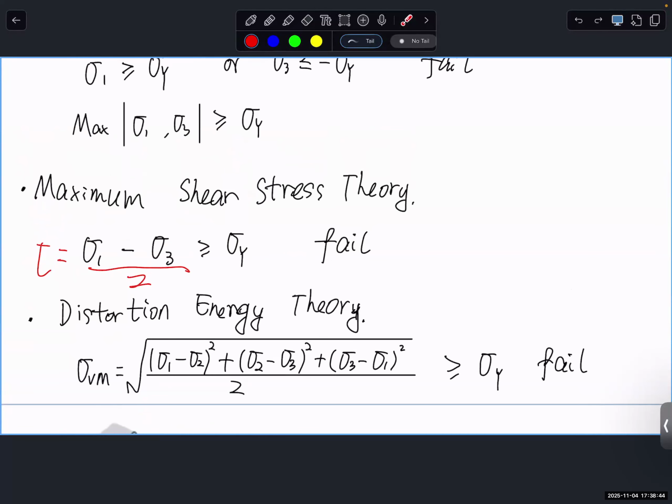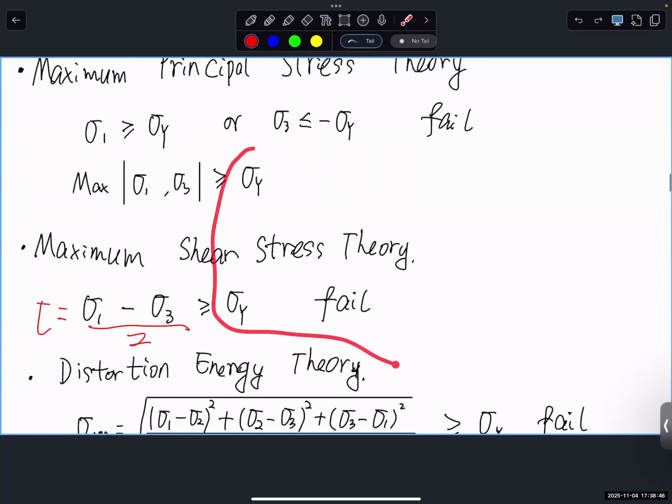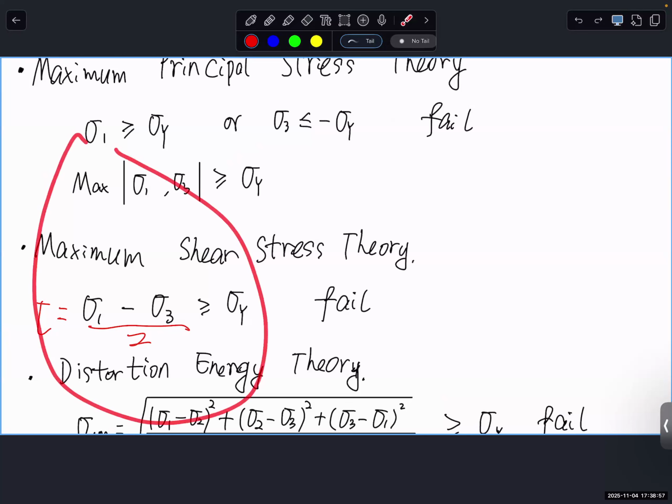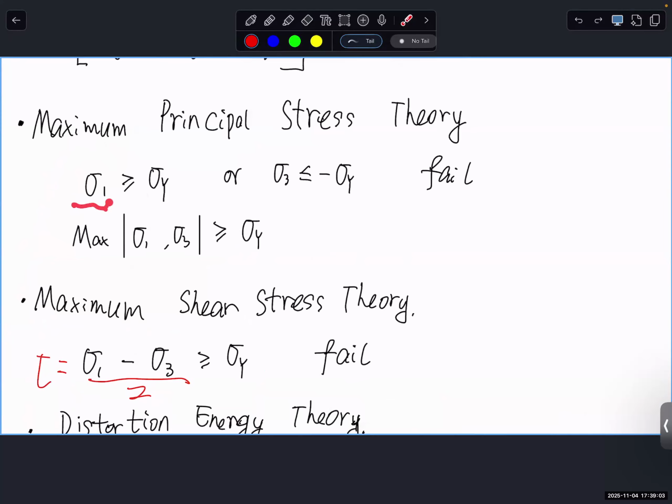So basically, for whatever material we have, we only do tension compression tests in the lab. And we test the yield strength and everything else. And everything on this side is the actual stress in your own structure, and you compare. If it's brittle material and the maximum principal stress exceeds the allowable stress of the material, it fails.